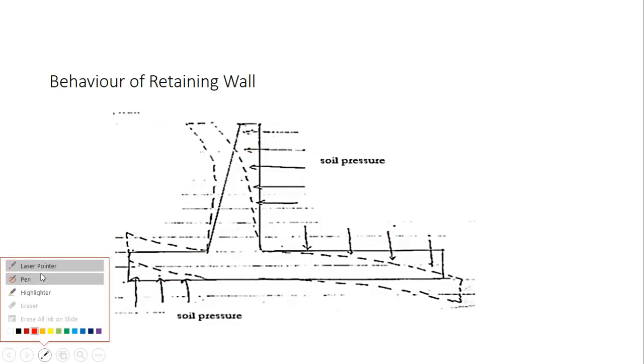Now on the toe slab there is no soil over here, so there will be no deflection in the downward direction, but I have told you that there was an upward reaction. So this upward reaction will now act on the toe slab, and as a result the toe slab will be lifted upwards. So from this diagram you can see that this portion is actually in tension.